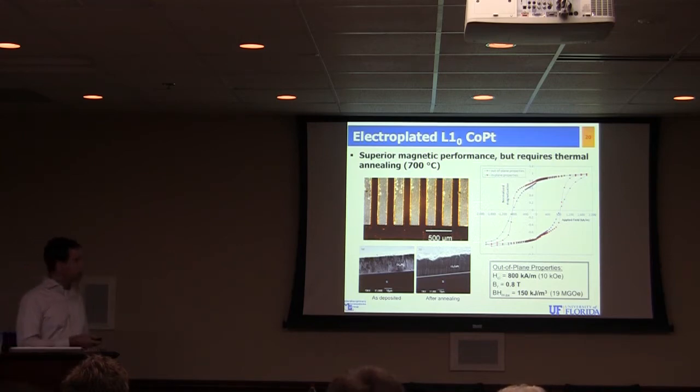Okay, so after the fabrication, we would take the magnet and we would pole it. We put it in a magnetizing fixture and put a single pulse field, just a quick pulse, to pole the magnet, either out of plane or in plane, whatever direction you want to pole it. Yes, at room temperature, after annealing. That's correct. And when you do these VSM loops, this is the applied field. This is the magnetization as a function of that applied field. That's what you're tracing out in that case.